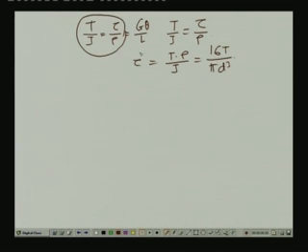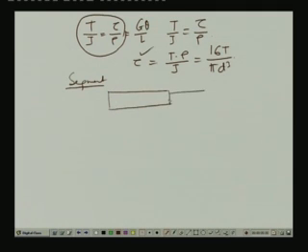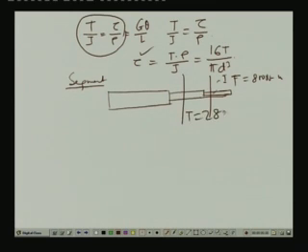Now, we need to compute the value of stress in 3 different segments. For segment 1, we have the values of the twisting moment. If we look into that, the shaft is a stepped one. Now, for segment 1, if we cut a section over here and take the free body diagram, then we will have a twisting moment as 800 Newton meter. For segment 2, we will have twisting moment as 2800 Newton meter, and for segment 3 we will have 5800 Newton meter.